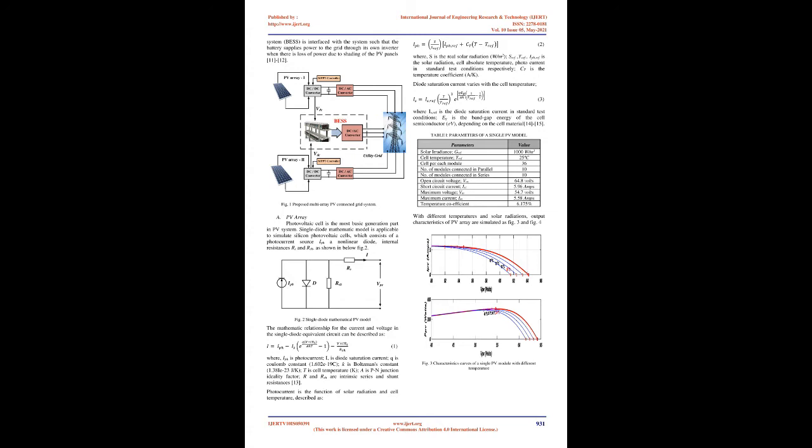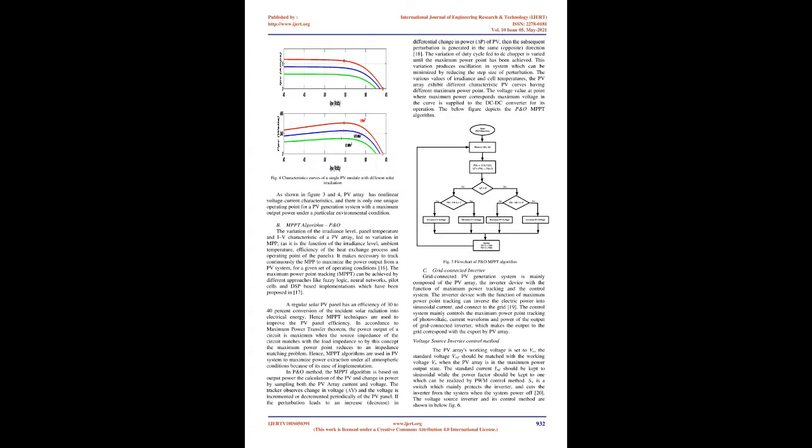For high power applications, it is common to divide the PV plant into several sections as seen in Fig.1. In each section, the PV array is connected to a buck converter, which is used to maintain the PV voltage at its maximum power point. It is reported that a buck converter has an advantage over other DC-DC converters when there are multiple strings connected in the array. The output of the buck converter is connected to a central inverter, which is typically a two-level inverter. The power circuit diagram of one unit is shown in Fig.